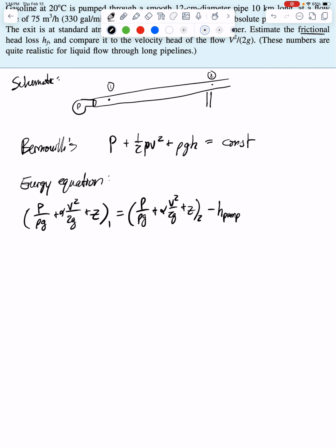On the other hand, if there was a turbine that is using the fluid from section 1 to generate power and divert the power somewhere else, or if there's friction occurring as you go from point 1 to point 2, the turbine and friction cause loss, which means that point 2 would have less energy than point 1 due to these two components. Therefore, we have to add the energy back to maintain this energy balance. So once again, we add the fluid height column of the turbine and the head of friction, which is head loss, essentially. And speaking of head loss, that's what we're trying to find.